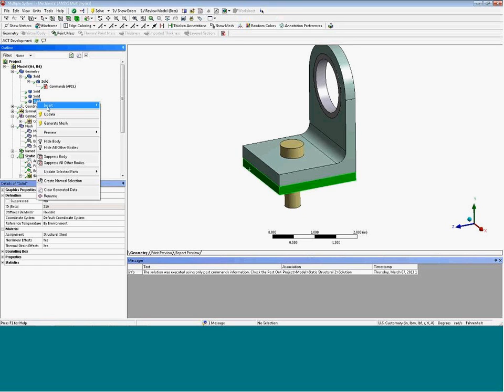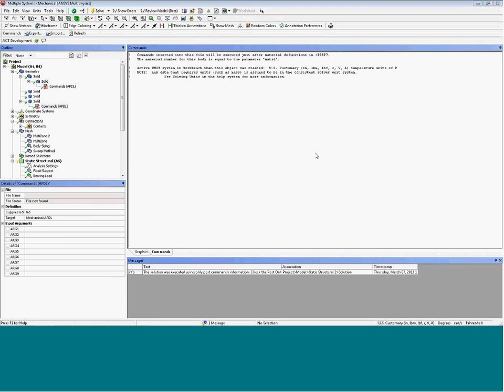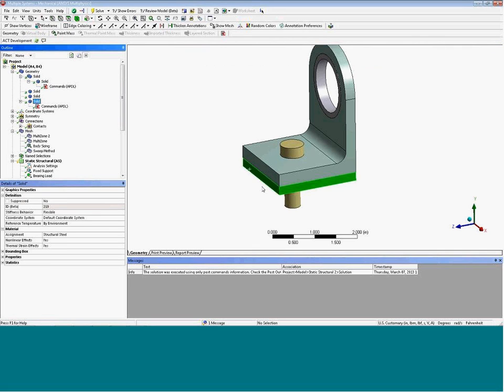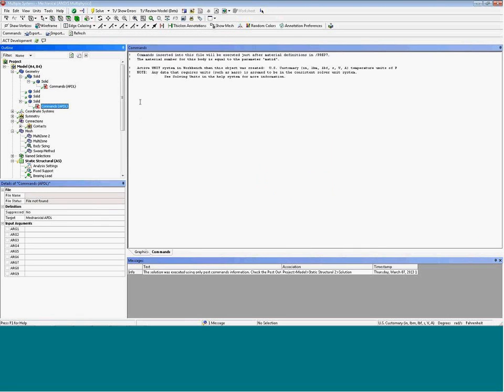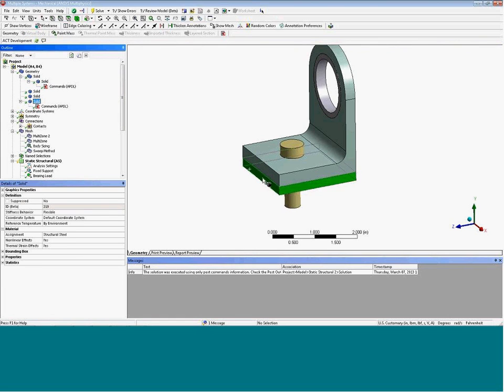On the solid body, I'll insert a command block, and then the parameter mat ID is equal to the material number. What's also true is that on this body, the element type, real constant, and section number can also be the same. So we can access the element type for that body through mat ID as well. And I'm going to change the key options for those SOLID185s. I'm just going to make it a layered solid, and then store all the information for all the layers with these two changes. That's easy enough to change some of the options on the element type.